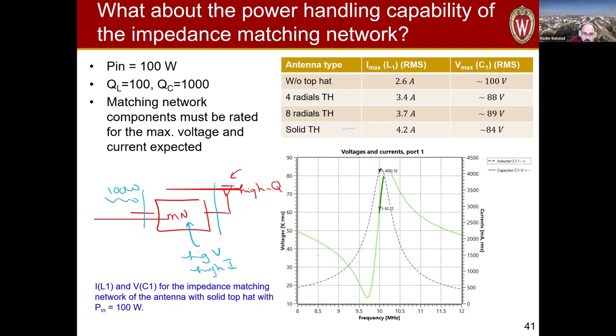Yes, absolutely. So the Q of the antenna, in this case, we're basically defining as the Q of any resonator. That would be defined as the ratio of stored energy to the dissipated power per unit cycle, and we also multiply this by 2 pi as a conversion factor.